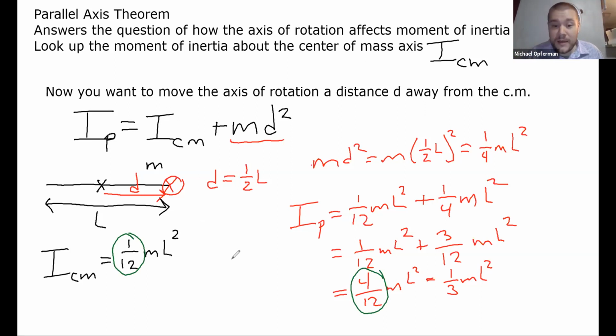But a lot of times these corrections are even more important than the center of mass moment of inertia. In this case, 3/4 of the moment of inertia is coming from where the axis is located, and only 1/4 of it is coming from the main properties of the object. So if you do this experiment again, like this, and then redo it like this, and you think about whether it feels 4 times heavier than it did, that seems pretty plausible. It makes a big difference going from here to here.